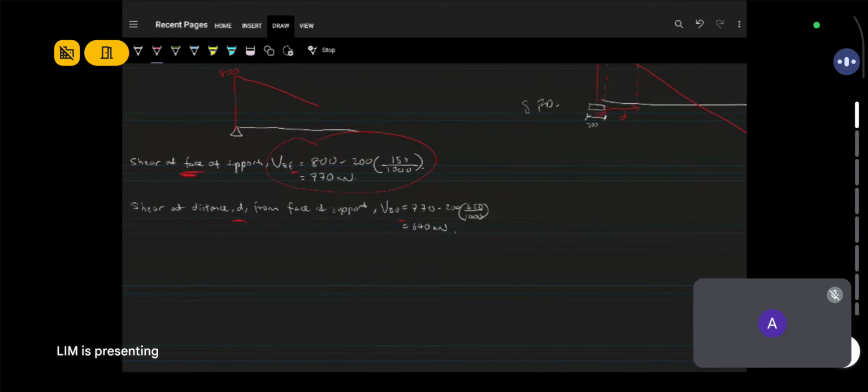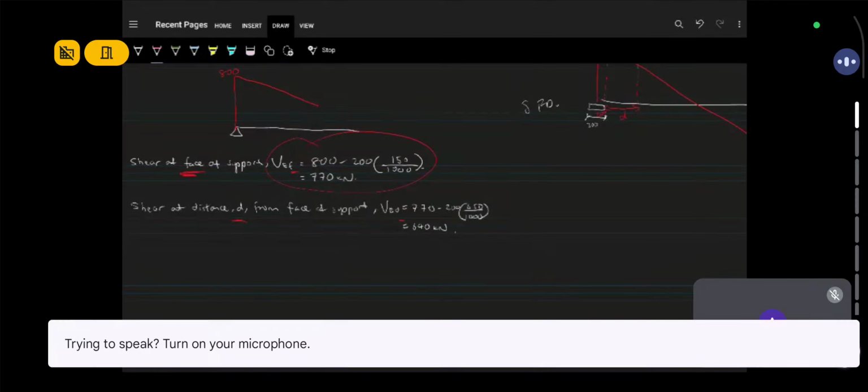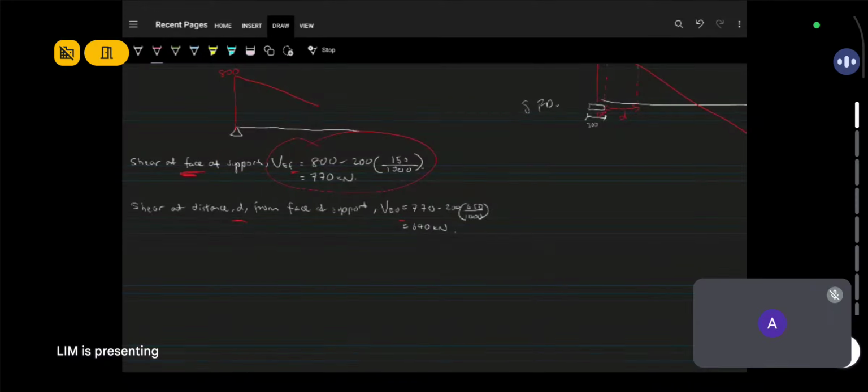I explained earlier, last week, that the way a beam resists shear in Eurocode is they assume this truss, strut and tie analogy. In other words, it behaves like a truss. It assumes your beam behaves like a truss.